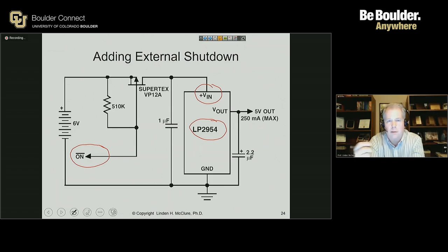If you are designing an embedded system where power, control of the power and battery life is important, this is one of those techniques that you might want to consider: power gating, turning off that downstream power users through switches.